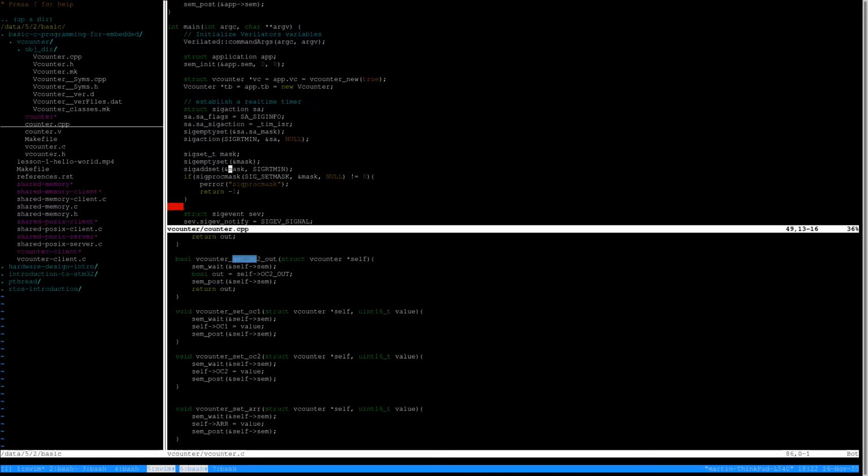The next thing I do is I want to temporarily disable the signal when I configure the timer. So I'm going to start the timer, and once the timer is running, I'm going to enable the signal so that I start receiving interrupts. So this is similar to disabling an interrupt and then doing configuration on a microcontroller and then enabling the interrupt again. Except that we are doing this on Linux, so we're using signals. And signals are very similar to how interrupts work in hardware, except signals are a concept used only in software, but it kind of simulates the same thing.